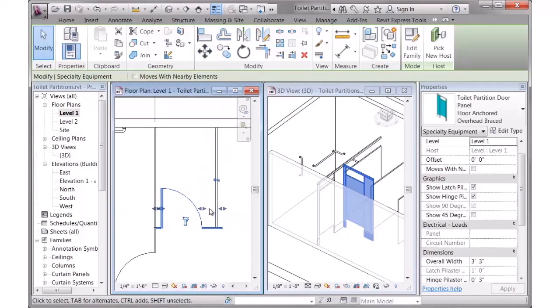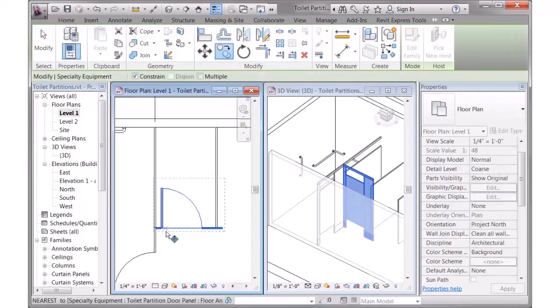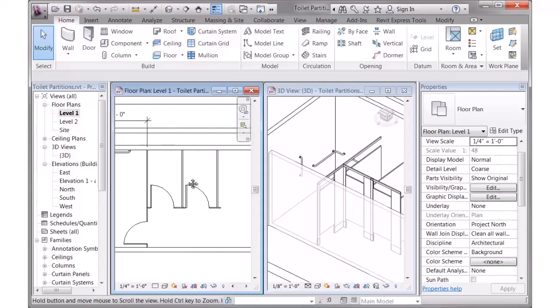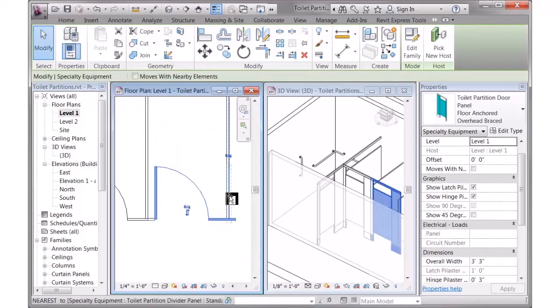Okay, so now it's hiding in front of that panel, and I'll just copy that over to cover the next object. So 3 feet is what I used before. And you can see your toilet panels are coming along. Now, a couple things here. This obviously overlapped a little bit too far, so you can click on the grips and you can stretch that into place.